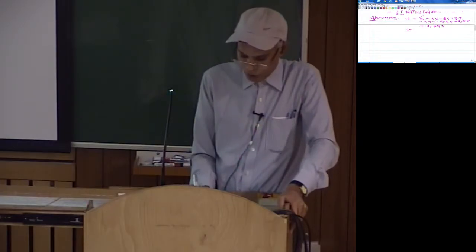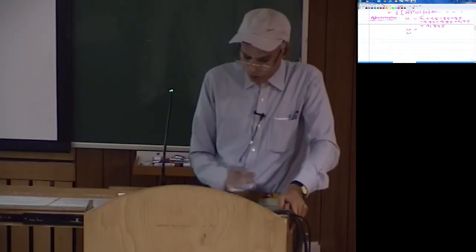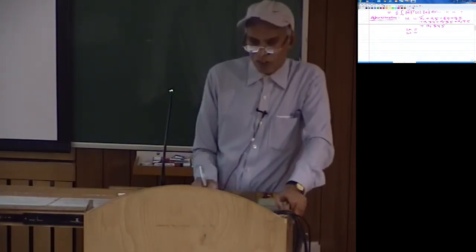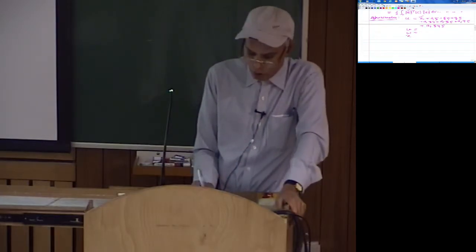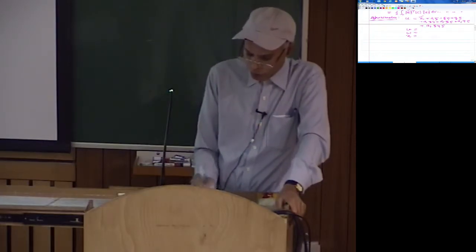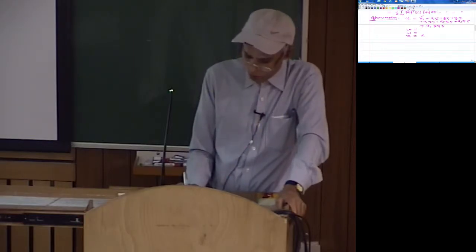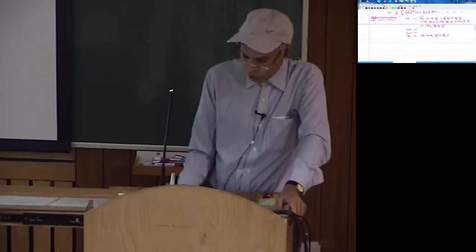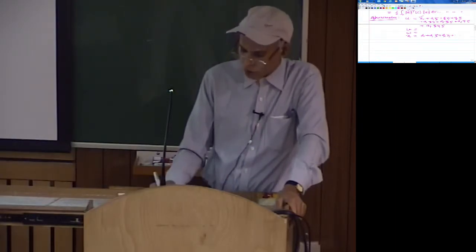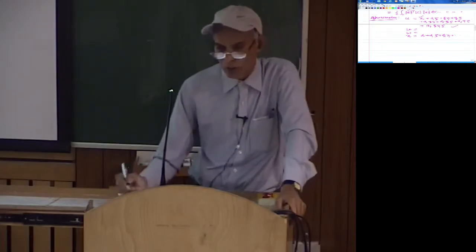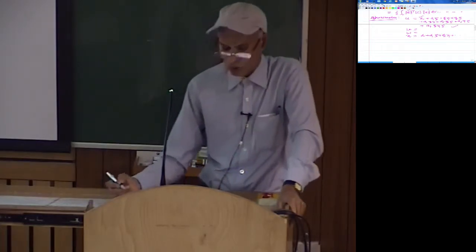Similar thing you will have for v, same thing for w, and since this is an isoparametric formulation, also for x, y and z. Say x is equal to d0 plus d1 into xi plus d2 into eta, and so on. This form is going to be similar to what I have written for u.